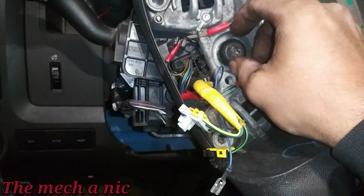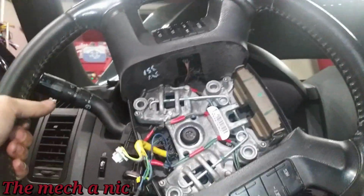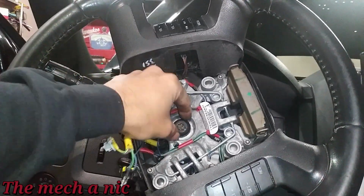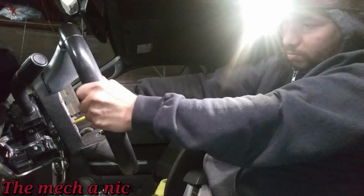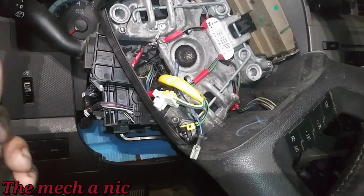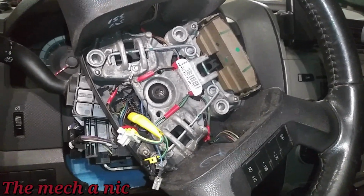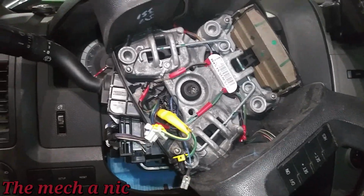But an easy way to get around this is to put the bolt back in it and just kind of leave it loose. All right, but basically you just want to rock back and forth on the steering wheel, holding it in two places, and it will come off. And there it goes. See, it broke loose. You don't have to go all gorilla on this thing, okay? You don't have to go crazy bashing it, hitting it hard, trying to break anything. Just give it some nice firm wobbles back and forth and it comes off.